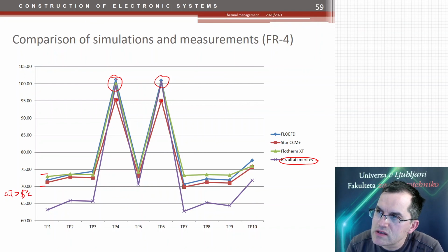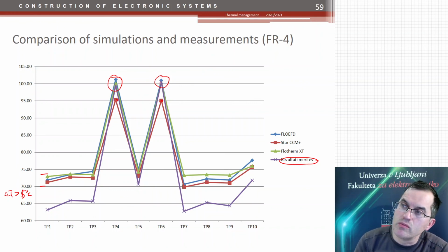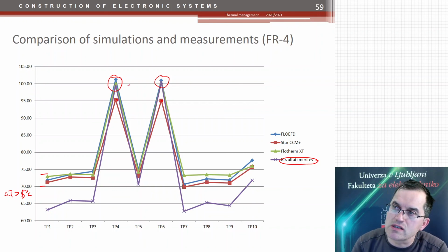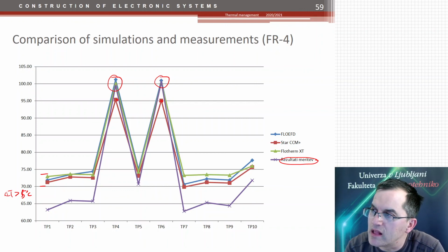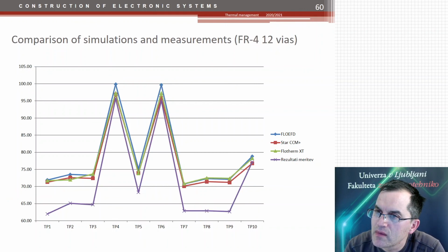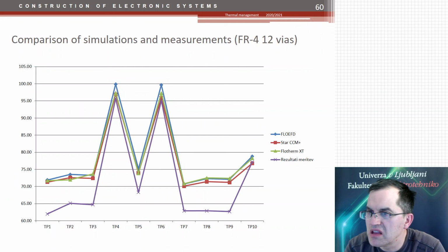While here it was a little bit closer. So I must say that the temperature or the heat transfer modeling was okay close to the source, and it was getting worse and worse going away from the source. So the properties of the PCB may not be so well defined. And even if you take the PCB without wires or with wires, it did not help a lot regarding the accuracy.